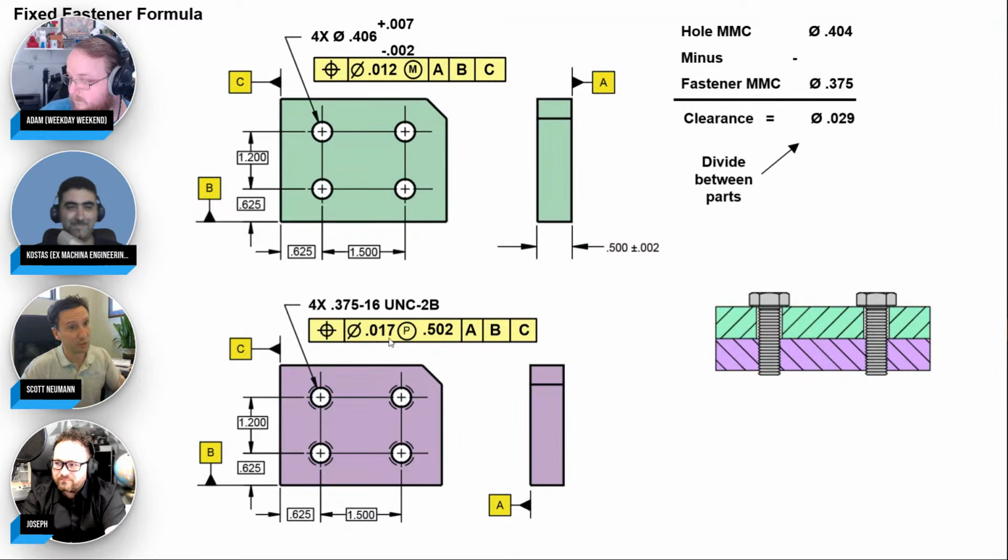But I can't give you 17 anymore because the minor and the pitch might have a coaxiality problem. They might be off 2 thou. So if you force me to do a minor diameter check, then I'm going to reduce the tolerance down to 15. And no, don't reduce the tolerance if that's not functional. So what I'm going to do is put 17 on there.